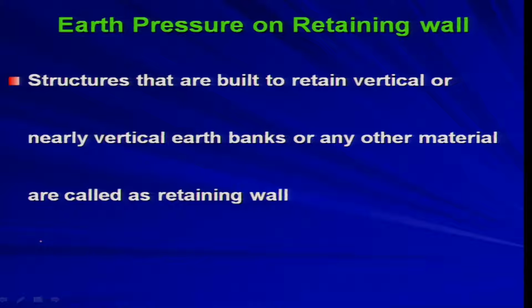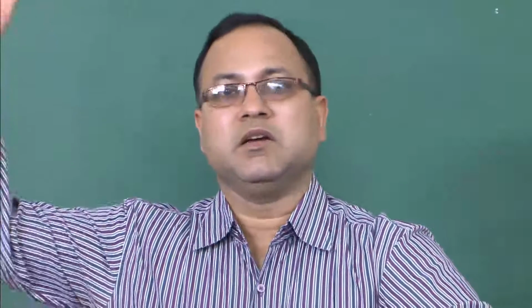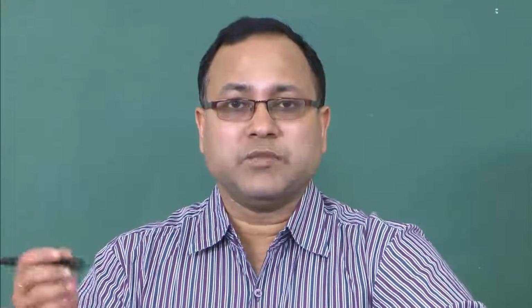This is very common in hilly terrain or hilly roads. If you travel to any hill station, you will see that on one side you have the mountain or the hill slope, and that is retained by some wall, a concrete wall or masonry wall or maybe rock masonry wall. To understand the stability of this wall, you need to know the concept of earth pressure, which is a very important phenomenon in soil mechanics.